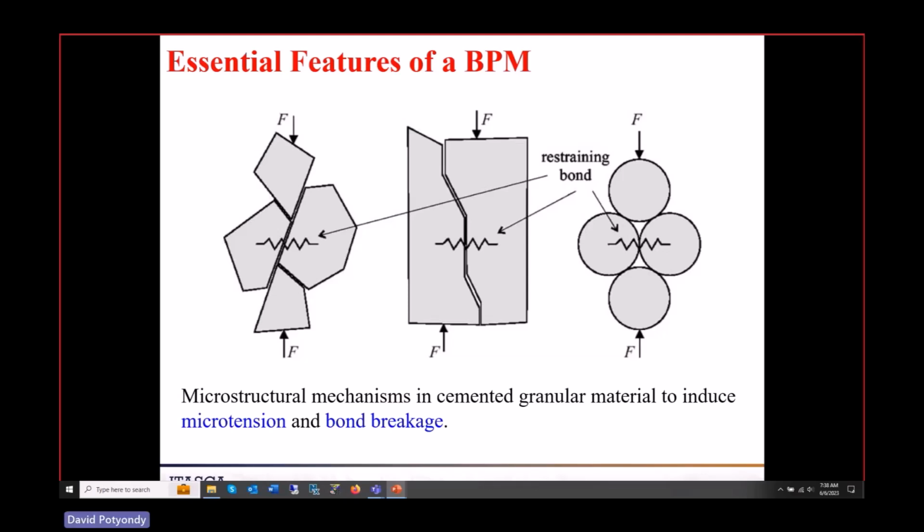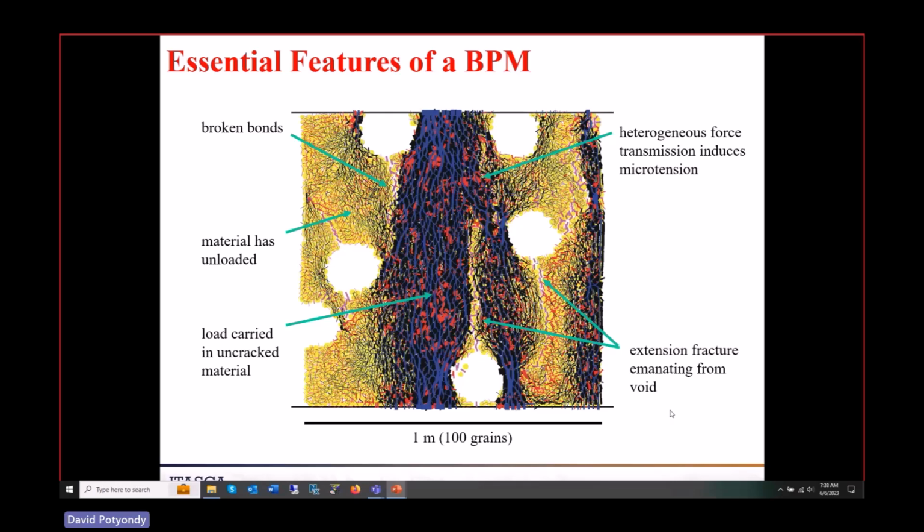because the tensile strength of rock is in almost all cases much lower than the shear strength, these are the locations that begin to break when you're compressing rock. Which means then, if you think of these broken things as microcracks that are oriented perpendicular to the spring, you are creating all sorts of small microcracks that are aligned with the sigma 1 direction. Okay. This is the key reason that this is making sense.